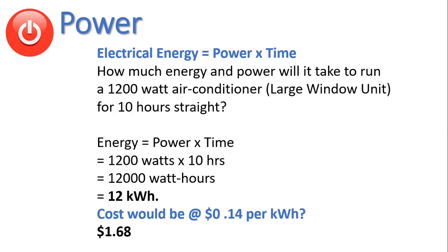But the amount that an air conditioner draws, the actual amount of watts it draws, is not always based on the rating of the air conditioner. So an air conditioner might be rated at one thing, but when you actually use it, depending on the moisture in the air and the temperature of the outside that it's doing the exchange with, you can really vary the amount of watts that's used. So just keep that in mind.